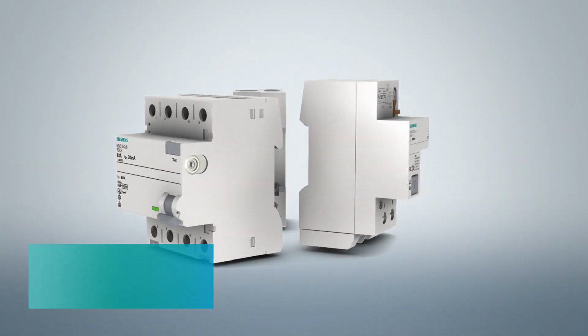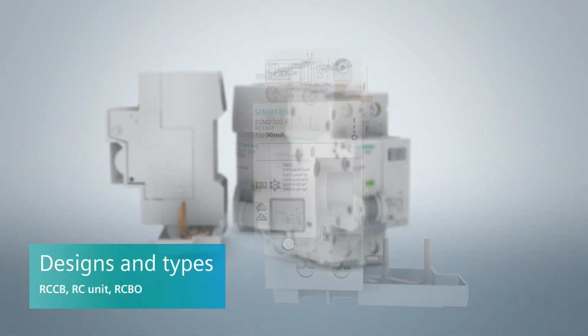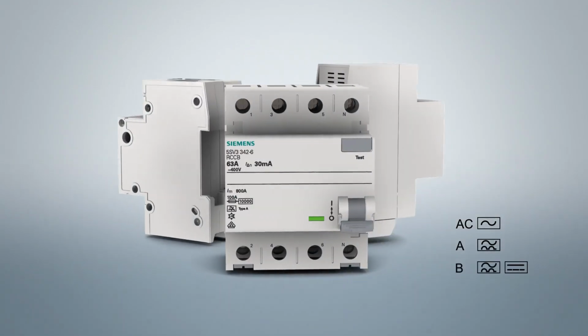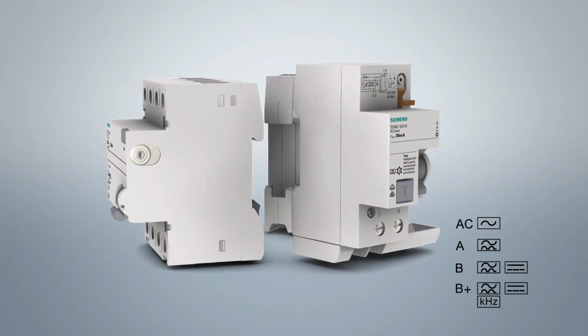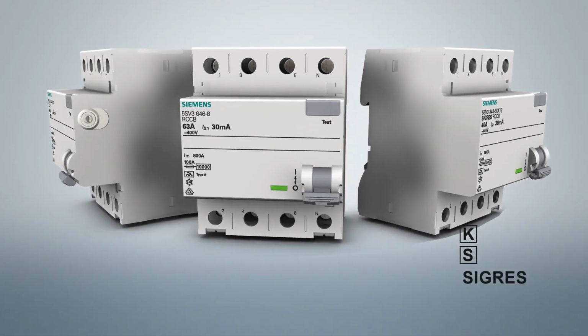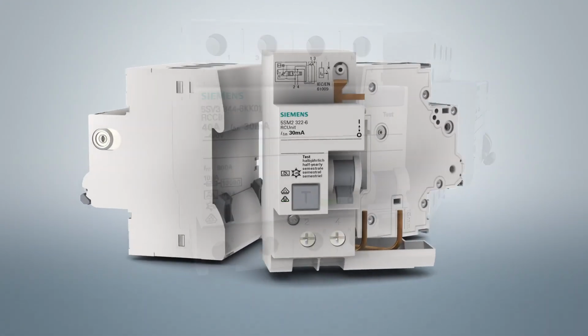We distinguish between various designs: RCCB, RC unit, RCBO in types AC, A, B, and B+, as well as different versions: super resistant, selective, and Residual. A short overview shows the meaning of these abbreviations.